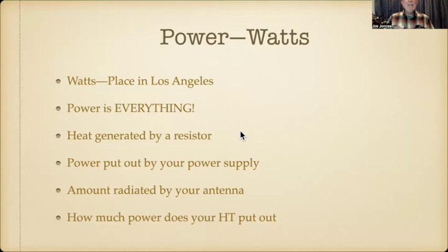That's why you have those huge resistors that I showed you, and smaller ones, and smaller ones. So if you're working on something and you find a resistor that's been burnt, don't put a smaller one in, because it'll just burn up as quick as the first one did. So fix the problem and then replace it with the proper size or bigger.